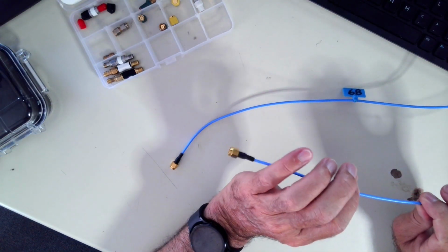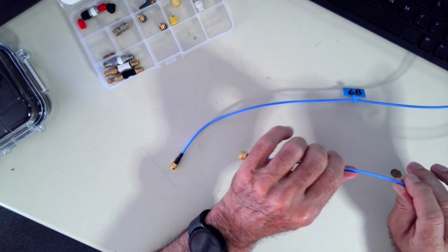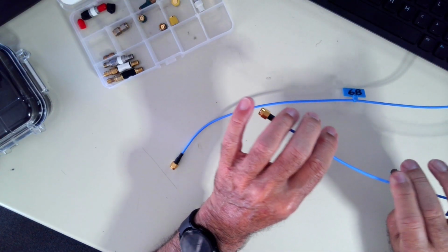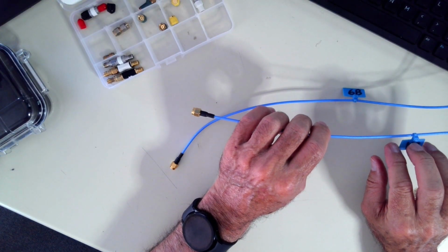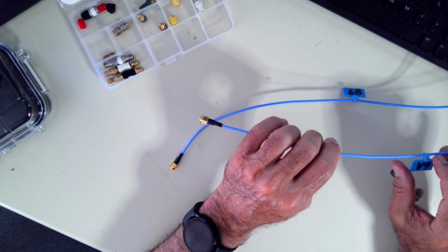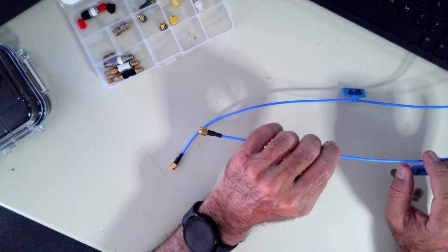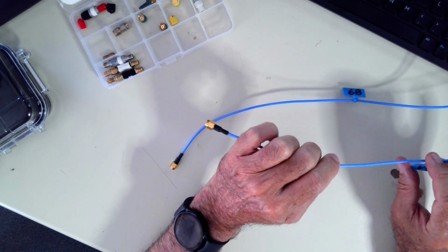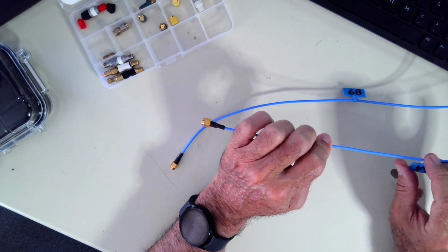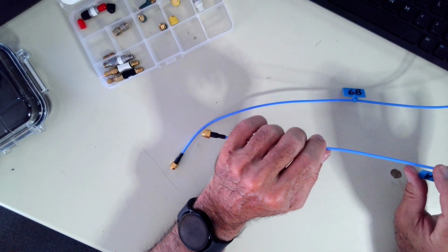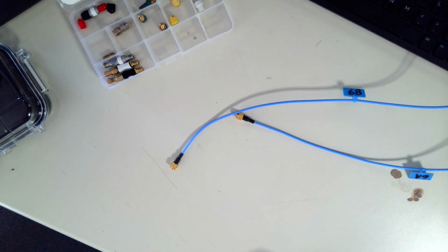One note of treatment of cables. Yeah, they're thin. Yeah, they're floppy and wobbly. Please don't put hard bends in them, because those bends actually cause impedance inconsistencies and pretty much render the cable useless. So treat these as you would any other precision equipment. We need to take care of them so they last. They cost us money to replace. We don't want to waste money. We need to keep that in mind. So please take care of the equipment.